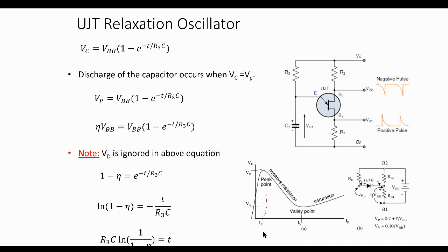All right. So tell them how you get the minimum now. Alright, so the minimum is actually right above IV, the valley point. So the voltage at the valley point is VV. So I would say it's the same VS minus the valley point voltage divided by the valley point current. Very good. Very good. That is all.